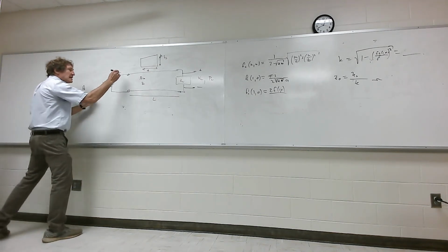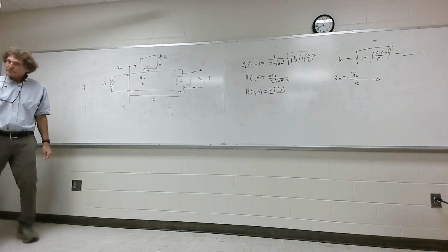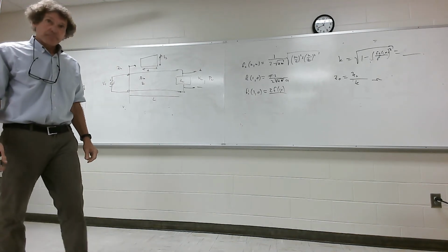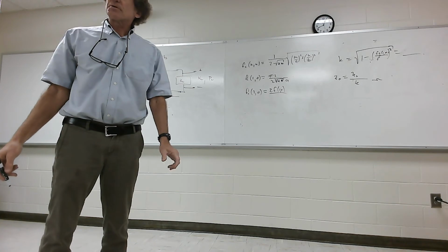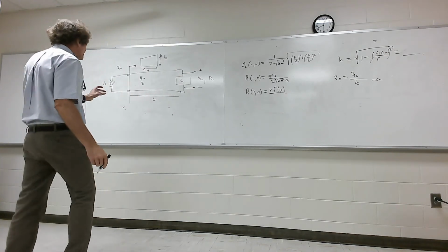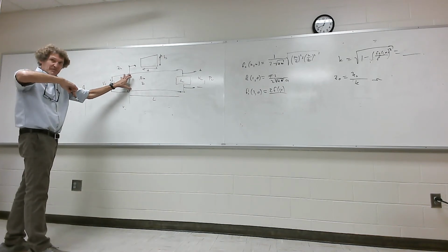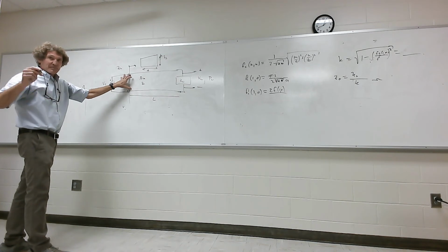Then I come here and I get the input impedance, don't I? Yep. Do you need to find input impedance if you don't have a source resistance? You sure do. Why? Because we have to remember the voltage that jumps right here is going to be equal to the forward going and the negative going. Remember? Yeah. And so we have to get that V0 plus. That's what I'm driving at now.